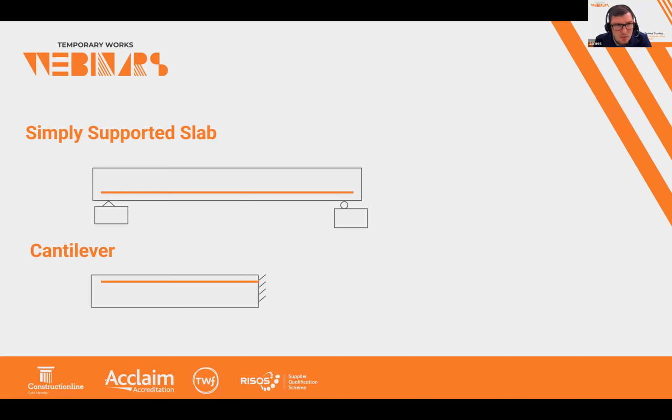I think there's an example in the cross reports from a few years ago that showed there were some cracks forming in a cantilevering slab, and the site team propped the end of the slab, and that's not a great idea. Essentially, you need to prop the whole slab if that's the case, because if you prop the end of a slab, it changes the load path and puts the bottom face into tension, and if there's no rebar there, you could be initiating the collapse yourself by propping it incorrectly. So just one little one to watch out for before I go into any examples.